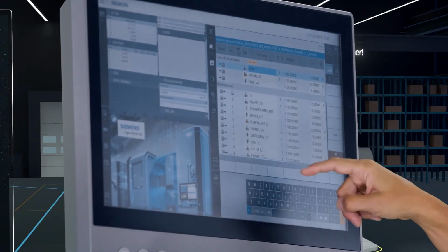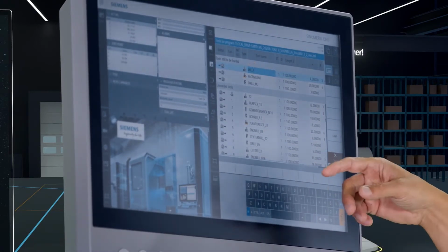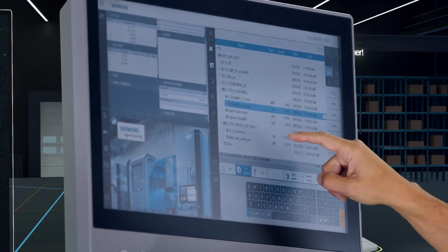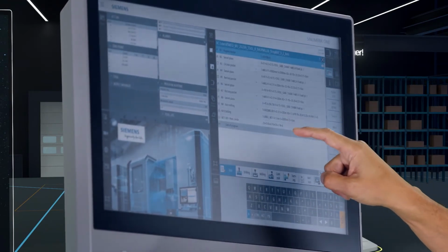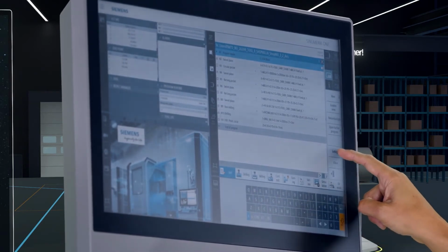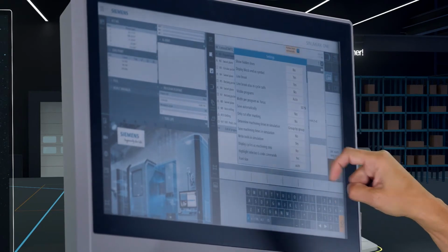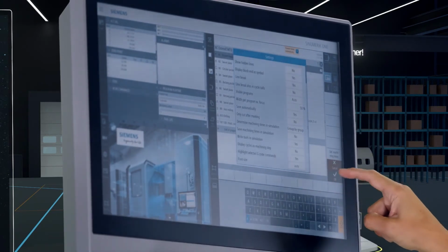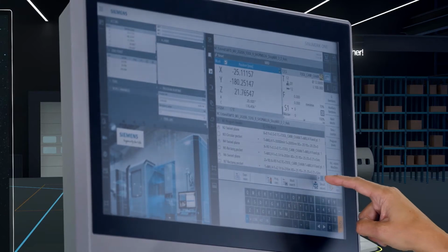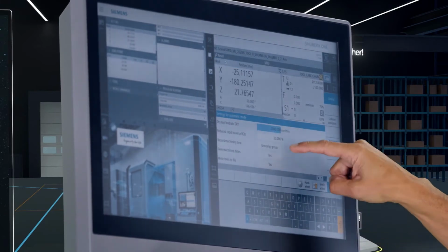With this function, we are able to load directly in our standard tool management list. As a possibility, we can use this function in either simulation mode, where we can adapt it under settings to write tools in simulation, or when you execute a part program directly on the execution, called settings, where we write this tool to a file.